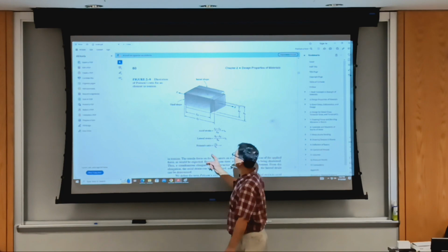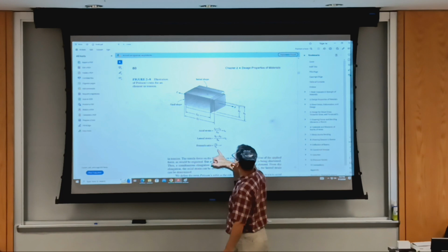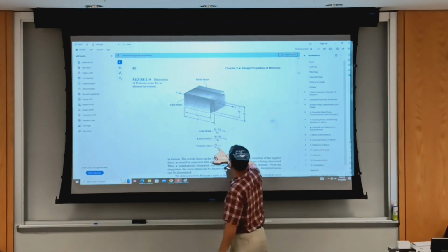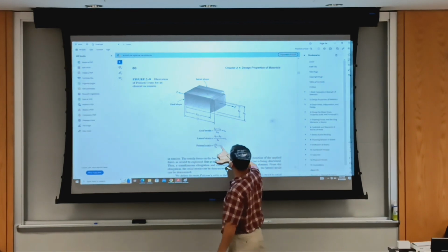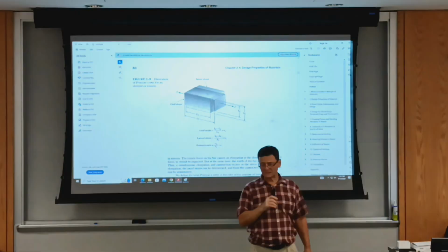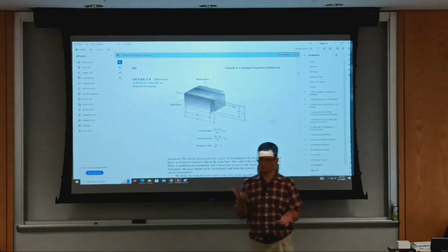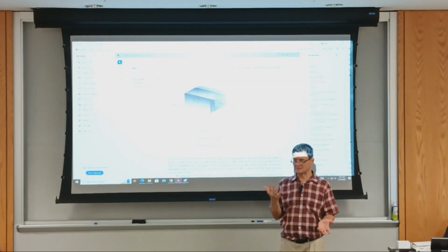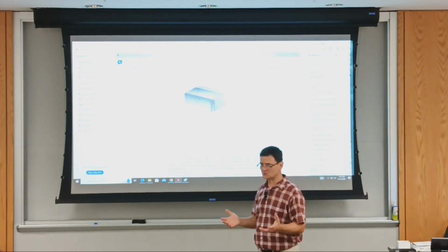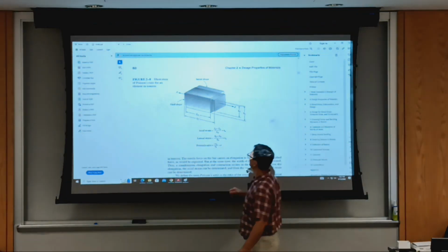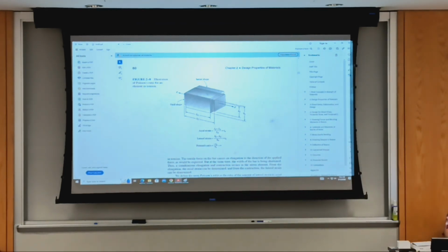Okay, now we have what is called Poisson ratio. Have you heard of Poisson ratio in material science? Okay, so maybe I should move faster with this. We take the lateral strain, which from this calculation ends up being negative, and make it positive. Take the ratio of the lateral strain over axial strain, and this is Poisson ratio. It's about 0.3 for most steel materials. Young's modulus also varies little between various steel grades. So if you're looking for stiffness, that is, if deflection is an issue, there's no need to go with higher grades just because of that. Anyway, so we have Poisson ratio as another property of the material.